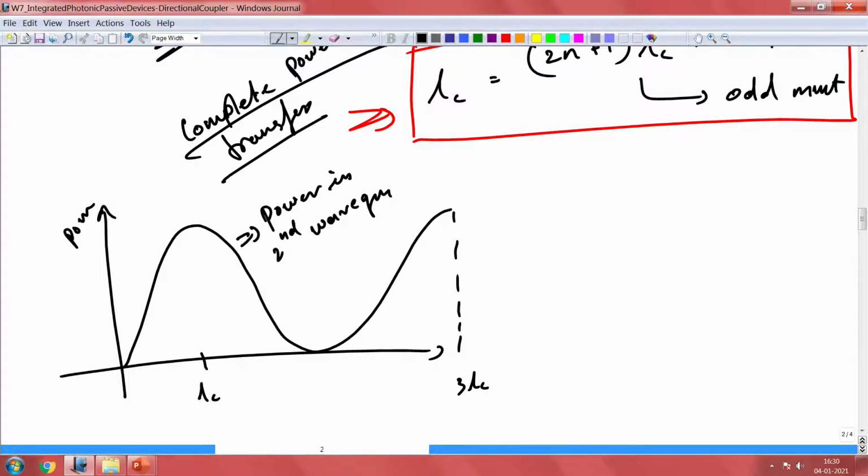So, you have two waveguides, right. What is the power coupling here and what is the length required in order to achieve that power coupling? So, this region we can exploit for other power, right. So, this is 1 of course and here is our 0.5, right, but you can get anything arbitrary that you want, okay, based on this curve.